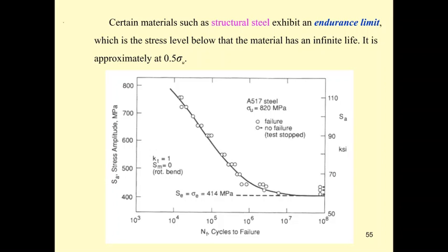Since we have the fatigue test, I have to mention the SN diagram. In the lab, we put stress into the specimen. If the stress is large, the motor will spin less. When we put less stress, the number of spins of the motor until failure of the specimen is going to be large. There is a point for certain materials that exhibit an endurance limit, at which the specimen never fails by fatigue.